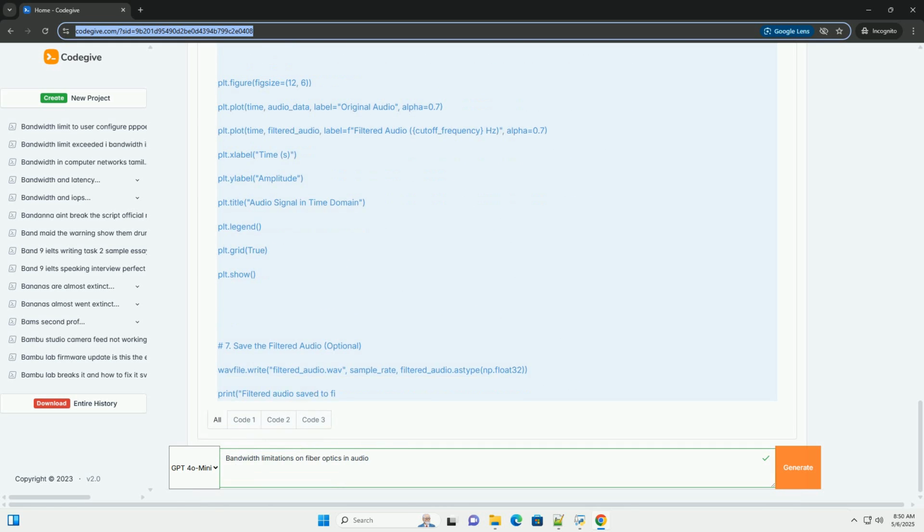Modal dispersion. Primarily in multi-mode fiber. Since multiple modes of light travel through MMF, each mode travels a slightly different path length through the fiber. This causes the different modes to arrive at the receiver at slightly different times, leading to pulse spreading. Modal dispersion is the dominant limiting factor in MMF systems. SMF largely eliminates modal dispersion, enabling much higher bandwidth.